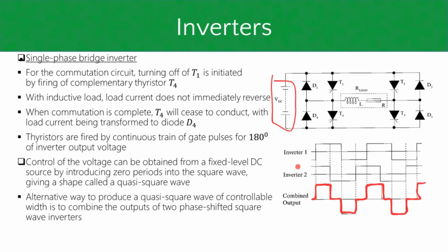Right, so that is if you have two inverters. You can have two single phase inverters supplying the same load. I think in this case, they're 90 degrees phase shifted from each other to build that. As you can see, if you add maybe a third and a fourth inverter, you can make this almost resemble a sine wave. And you do get pure sine wave inverters as well. It depends on the switching method that you use.